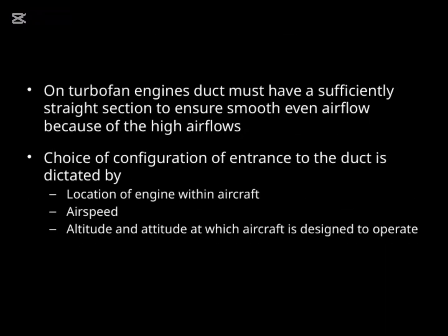When it comes to turbofan engines, one critical aspect is the duct design. The duct must have a sufficiently straight section to ensure a smooth, even airflow. This is especially important because of the high airflows involved, which can easily become turbulent or uneven if the duct isn't properly shaped.